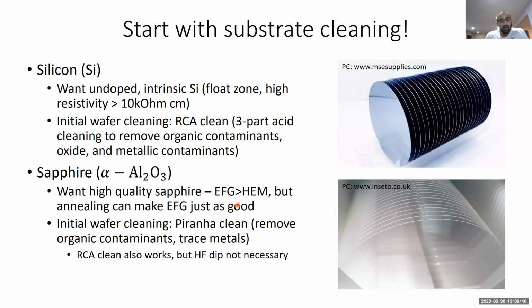For the cleaning, you can also do an RCA clean for sapphire, but because there's no distinct amorphous surface oxide like there is in silicon, you don't really need to do the HF dip. And in fact, at Yale, we really just do a piranha clean to remove organic contaminants. I'll also say that